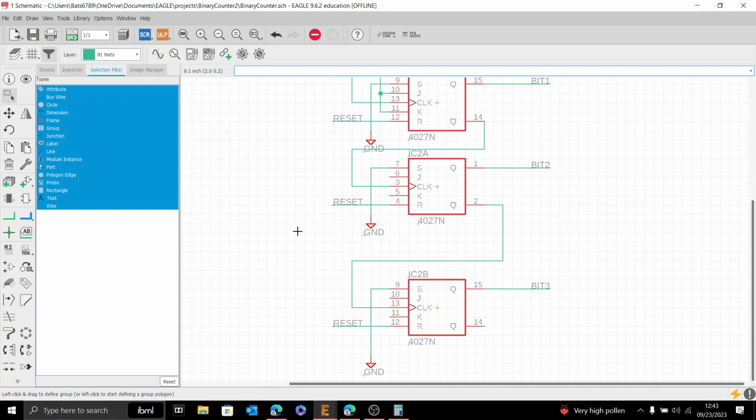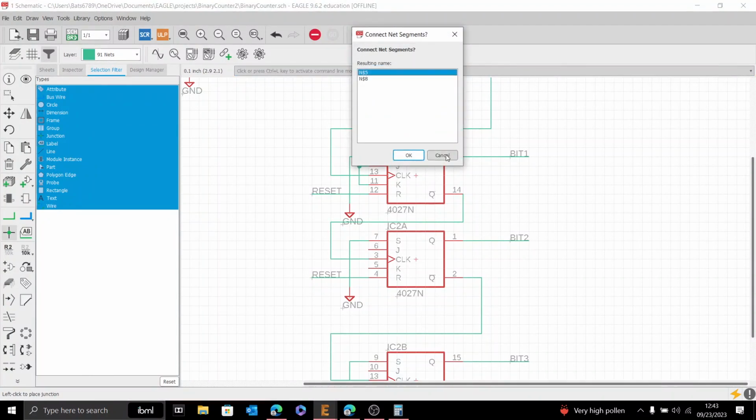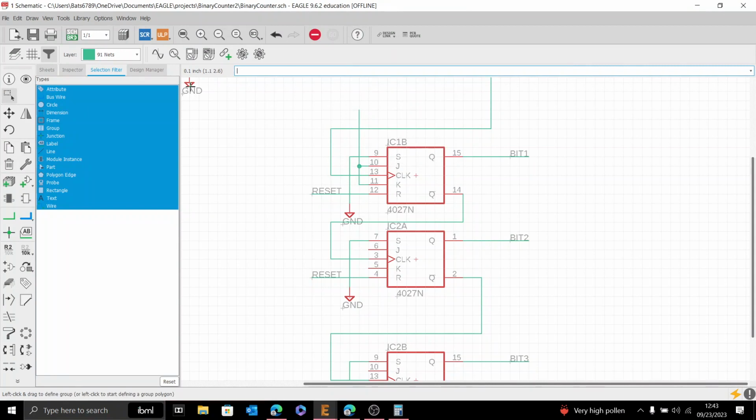Oh, the wires? Okay, yeah, the dots are junctions, and for the most part, they appear automatically. You see how I deliberately attached it there and then added a junction, whereas if you just run the wire through, it doesn't make one. This is just notation, basically: if there's no dot, it's not connected. It did it automatically, but I can come down here to junction and add one manually if I want to. So, a couple ways to do that.